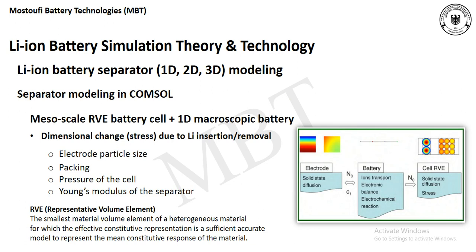The next software that we're going to discuss for separator modeling is the COMSOL software, which is one of the best softwares in battery modeling because it has different modules and different capabilities for designing the battery. For separator modeling, there is an option of coupling different models that are available in COMSOL, and here is coupling a mesoscale RVE battery cell with a one-dimensional microscopic battery.